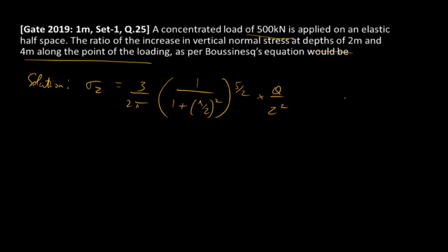Here they have asked us to find out the effective stress along the point of the loading. So r will be equal to 0, which gives sigma z is equal to 3q by 2 pi z square.